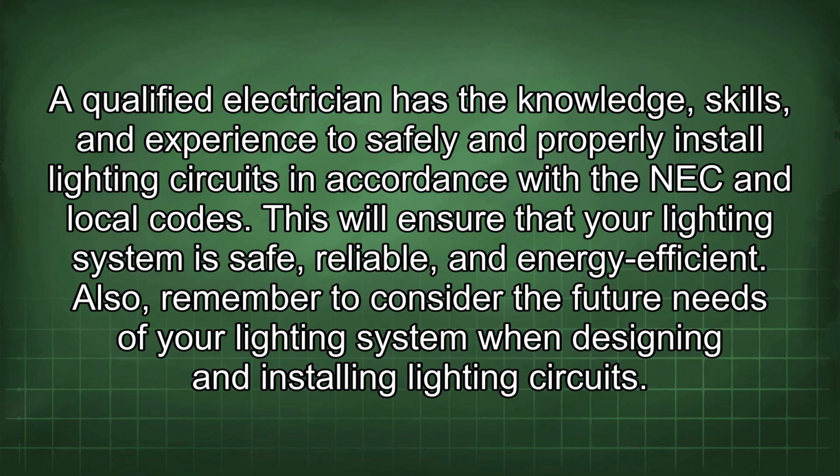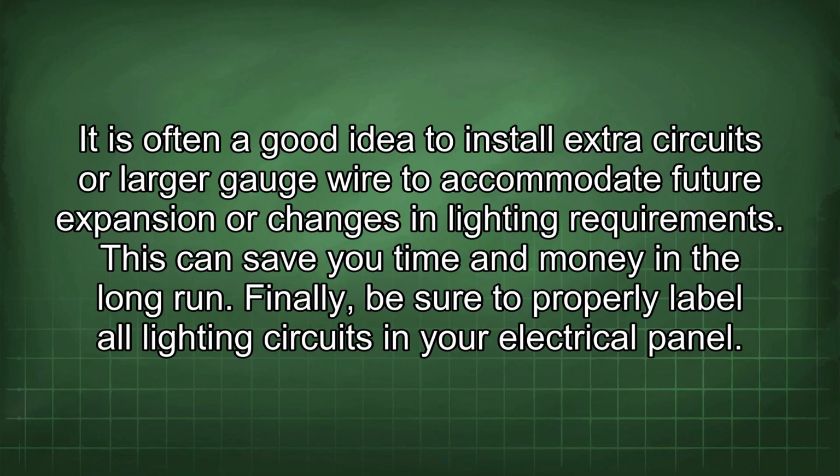Also, remember to consider the future needs of your lighting system when designing and installing lighting circuits. It is often a good idea to install extra circuits or larger gauge wire to accommodate future expansion or changes in lighting requirements. This can save you time and money in the long run.